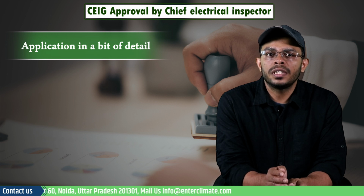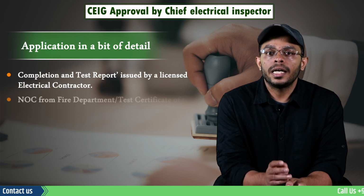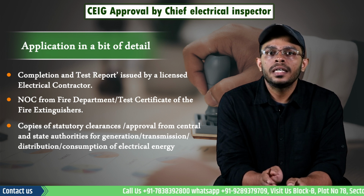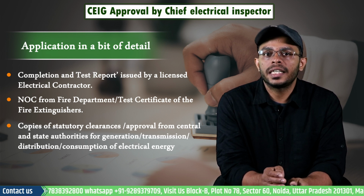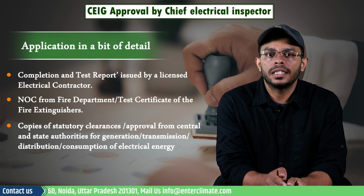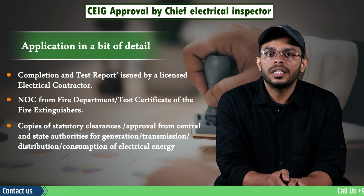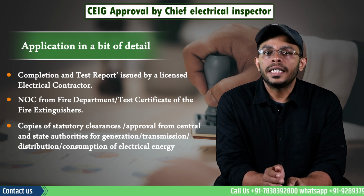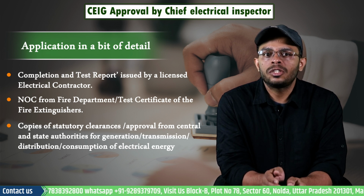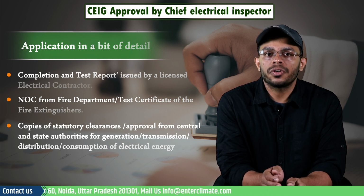The documents needed along with the applications are the completion and test report issued by the licensed electrical contractor, NOC from the fire department, test certificate of the fire extinguishers, copies of statutory clearances, approvals from the central and state authorities for generation, transmission, distribution, consumption of electrical energy. The single line diagram of installation showing size, rating and details of protection, details of loading and metering system, details of earthing provided for the proposed installation, copy of licensed electrical contractor and supervisor's permit, copy of challan of the inspection fee, undertaking for the safe operation of the installation.